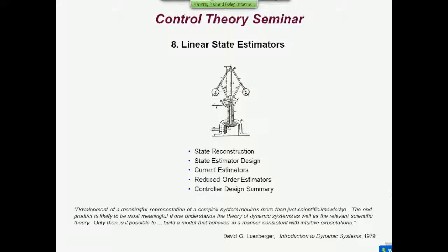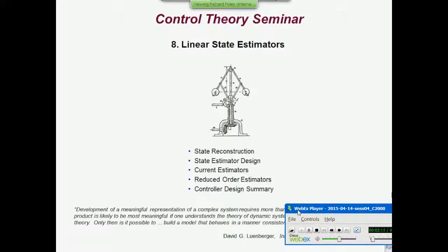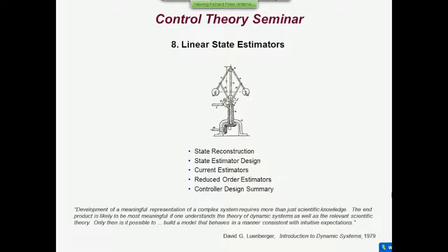But the technique that you use to design the estimator then changes quite a lot. And the estimator which results is called a reduced order estimator because its order has gone down by the number of measurable states. And so I'm going to show you that way as well. The main advantage in the reduced order estimator case is not a performance improvement, but a computation efficiency.